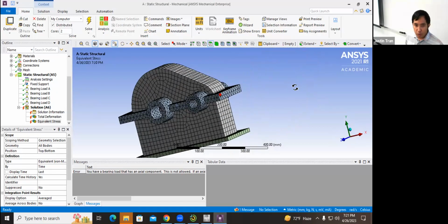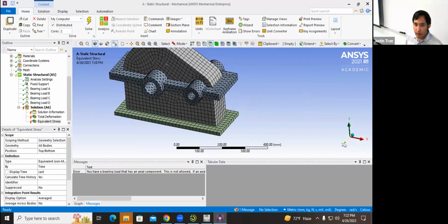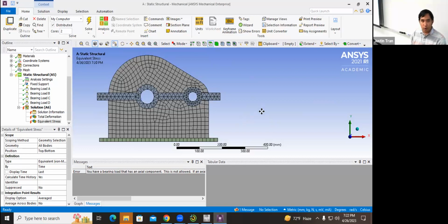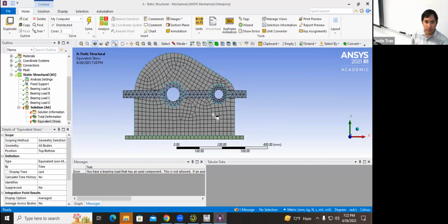Okay. And so, let's go back to our definition for the bearing load. The bearing load basically assumes that the rod is being pulled in a certain direction, and we're concentrating a lot of that force on that surface. That's only true if your force is in plane with the bearing hole. We have a nice case here because our flanges are aligned perfectly with the z-axis, so all of the holes are pointed in the z direction.